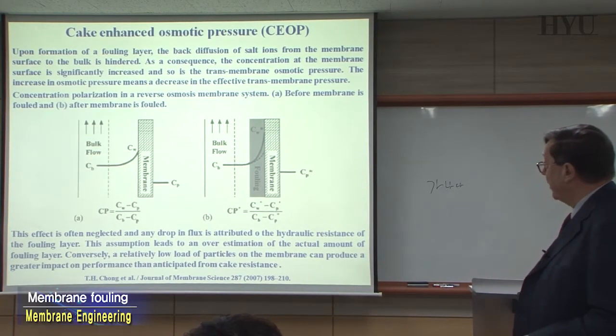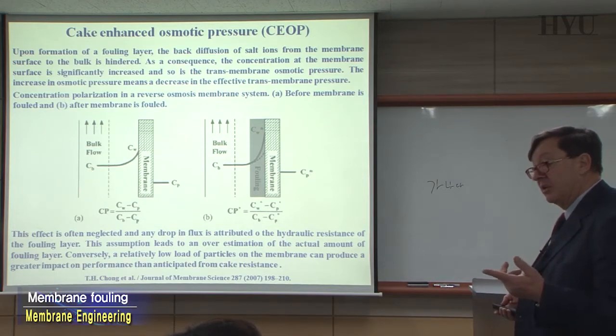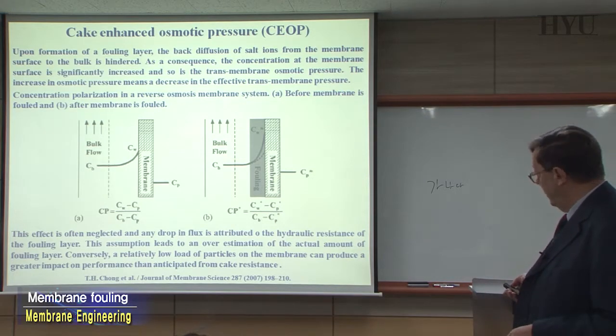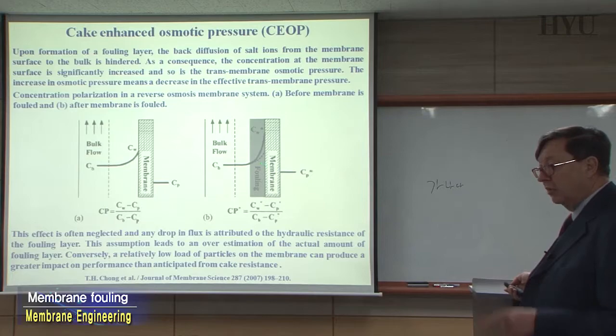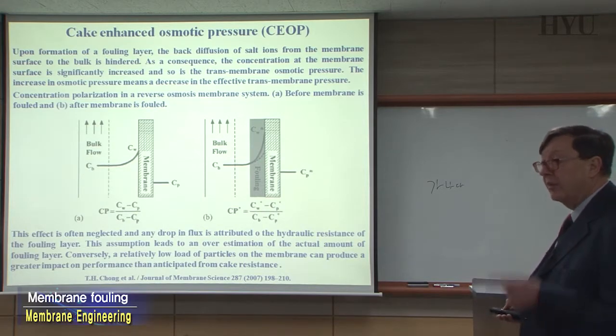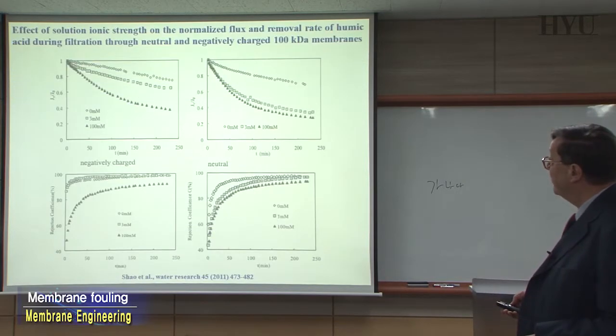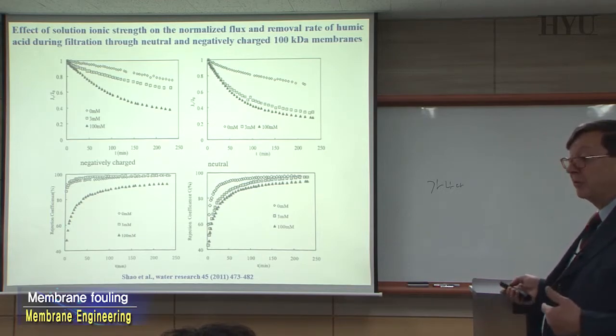And that is the one correction that today is becoming relatively normal. Now, in the past, people were just making mistakes, because they were assuming that just for increasing the transmembrane flux, they had to reduce just the thickness. It was not the case, because part of the problem they had was not related to the thickness, but was related to the different concentration at the interface, to the osmotic effects that are present. And here is a typical case to confirm this kind of observation.